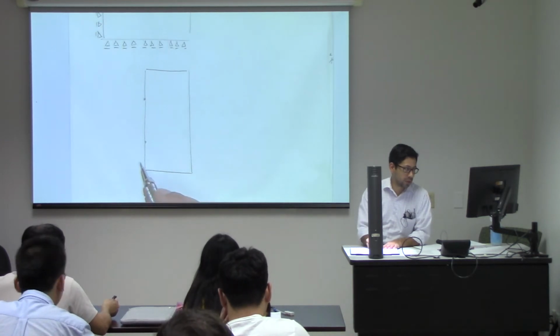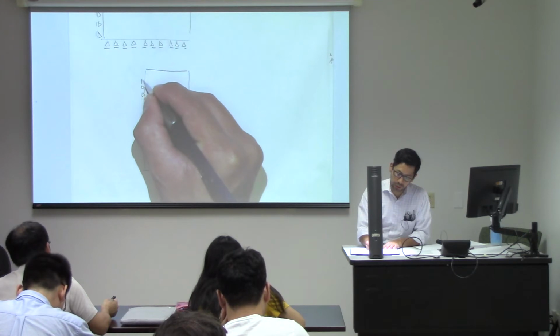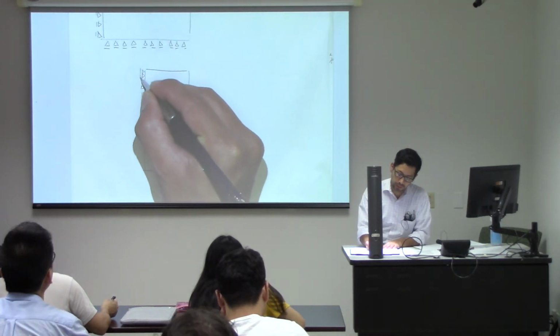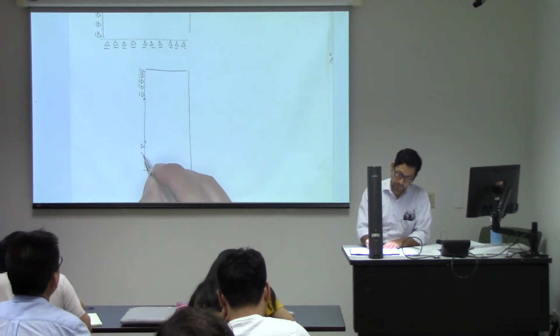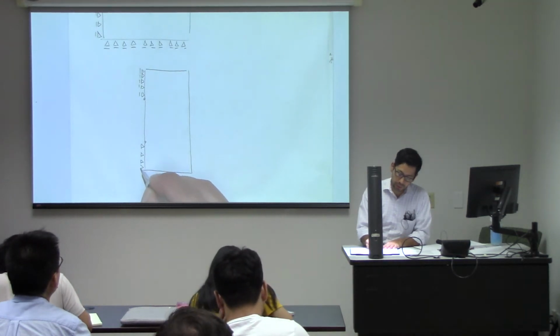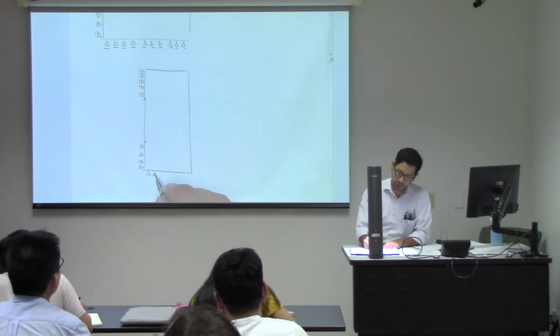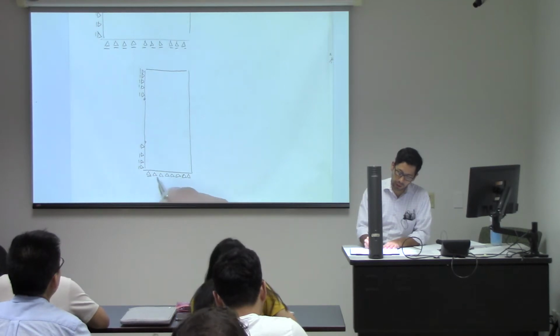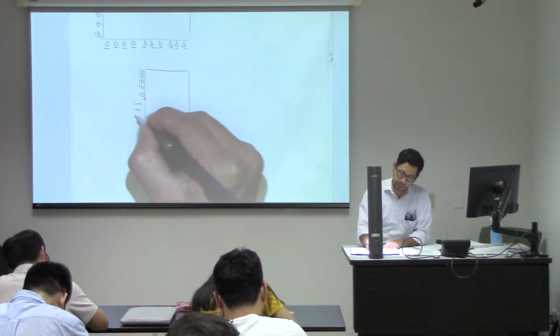Probably you want this section a little bit larger. But you could tell this boundary not to move in this direction, and this is just a straight line. Also, you tell this boundary not to move in this direction, and you have this one not to move in direction y. And here you just apply a pressure.